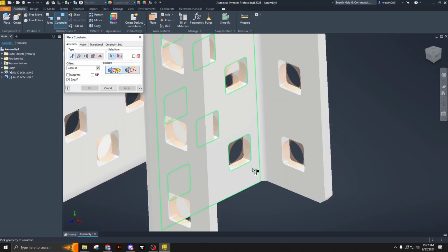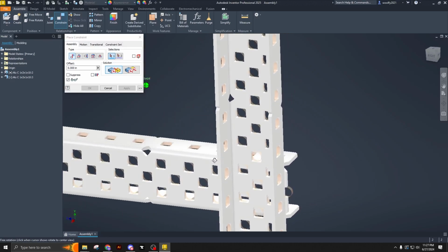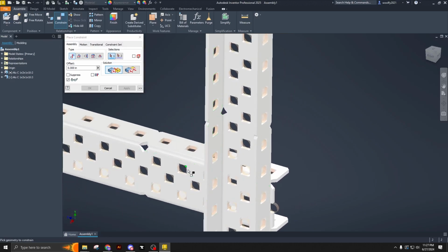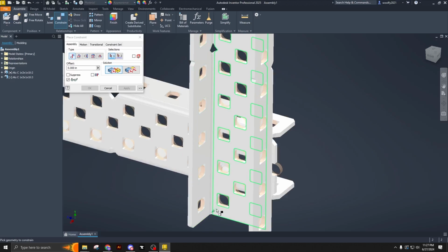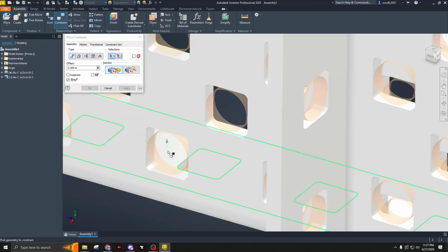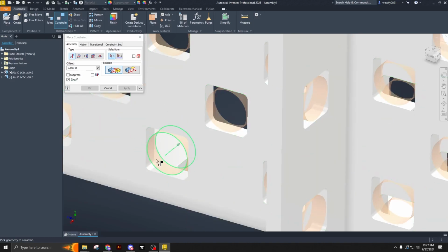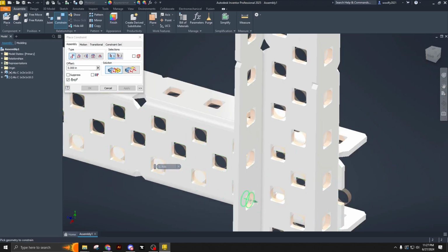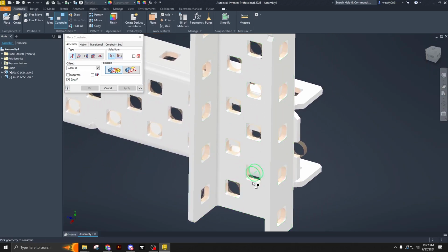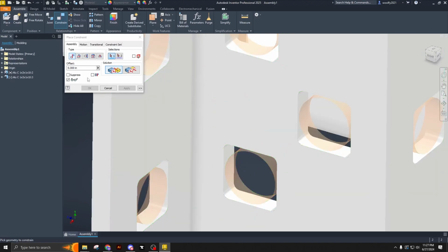So my third and last direction, and now this is where the VEX CAD library comes in, and why I used it as the base of the library I plugged in episode 0, is they've included these transparent holes that you can constrain to. It actually makes it pretty easy to constrain pieces of metal together and other circular objects.